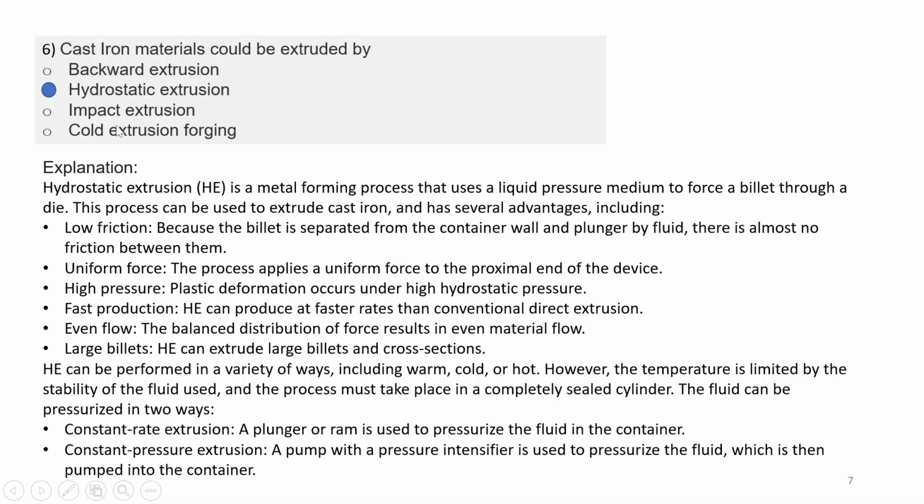Cold extrusion won't be providing you with much ductility here as well. In case of hydrostatic, you can perform it at lower temperature as well, but hydrostatic extrusion is very much preferred for cast alloys like cast iron. And also there is no friction acting as well in case of impact.